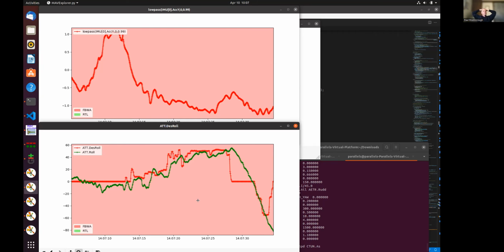The reason I'm thinking that this aircraft either wasn't trimmed straight or has a differential thrust issue is that even when it banks back the other way, you can see it still wants to yaw in that one direction. It's still got that side slip to the right. That's interesting.